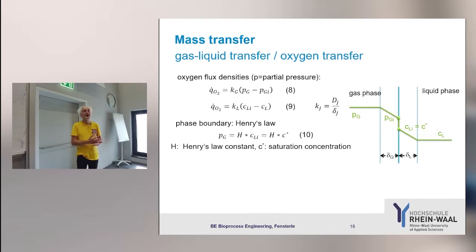And if you have a liquid with a higher solubility of oxygen, and the same concentration at the end, then of course the transfer rate will be way higher. That's clear. You can better dissolve it, so it's faster to dissolve. This also means that in reality, if you need to dissolve something which is hardly soluble in a solution, even if you have a large volume, it takes very long to dissolve it. This is the problem, because the driving force is very low.